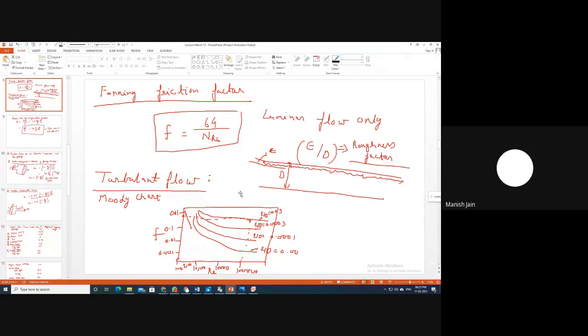And always remember, where energy balance is happening, the energy balance is per unit mass. The Bernoulli equation as defined is per unit mass, energy per unit mass. But where you have to give the power output for the system, that should be given in energy per unit time. Power of the pump, power of the system, electric power requirement should be given in energy per unit time. So multiply with the mass flow rate, and it will convert it into energy per unit time.